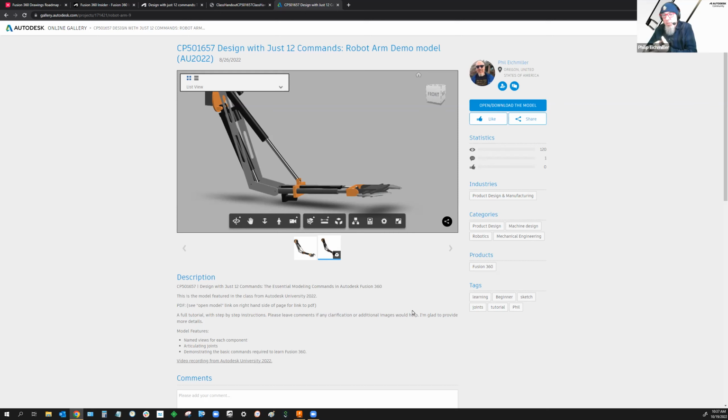It really does try out almost every single option in there, and then also joints in motion, various ways of applying a joint. Like, do you model things in place and then add an as-built joint, which is something you can't do in other CAD programs, or do you model it out of place and then move it into place using a regular joint, or what we call a joint.